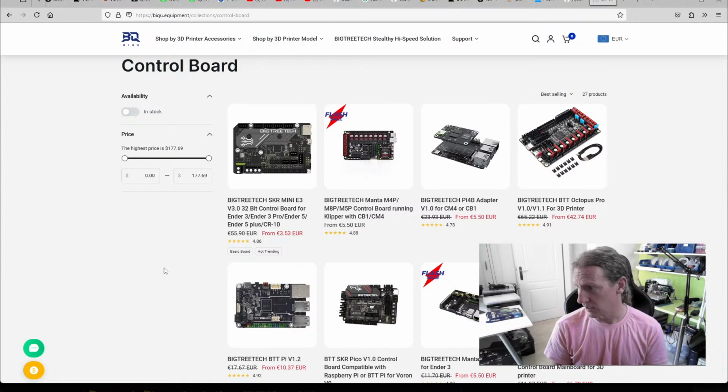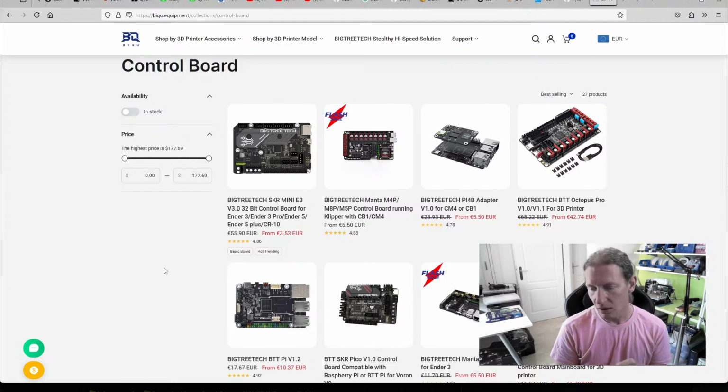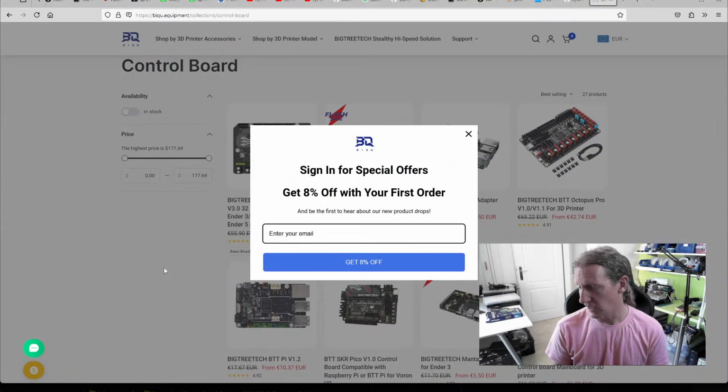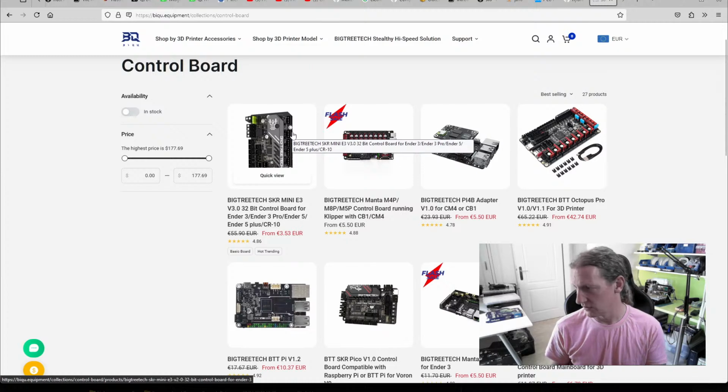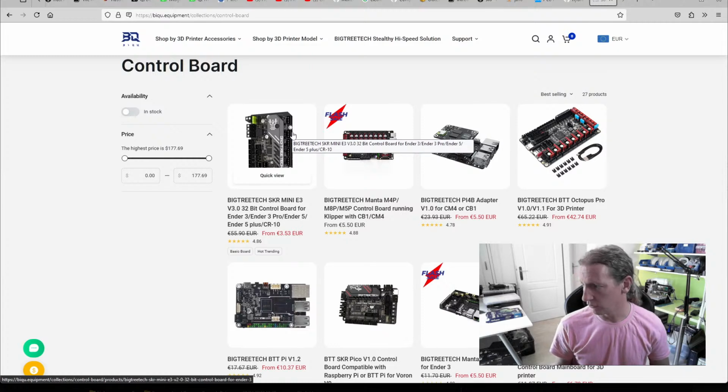Pick and place machines, on the other hand, don't have extruders, but they often have pickers instead, which need more axes. So they have the X, Y, and Z. The X and the Z control the nozzles. And in some machines, there are multiple stepper motors for the nozzles. So they sometimes have a stepper motor per nozzle.